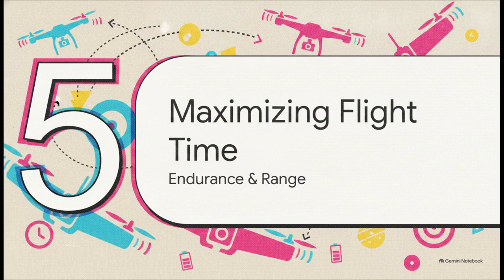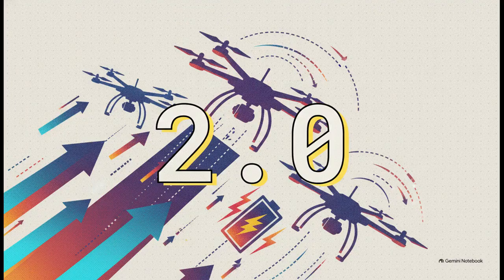All right, moving to Section 5, maximizing drone flight time. Well, maximizing time actually starts the exact moment you leave the ground. Taking off isn't just hovering. It requires vertical acceleration from zero. Our sources show that for vertical takeoff dynamics, industrial drones are specifically designed to maintain at least a 2.0 thrust-to-weight ratio. Having double the thrust required just to sit there is a vital safety margin needed to overcome the massive initial current draw when you're trying to break gravity's grip.